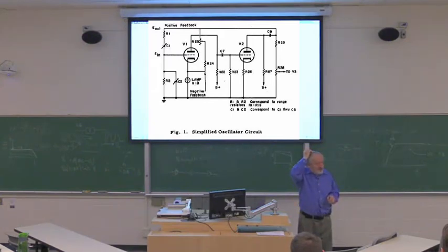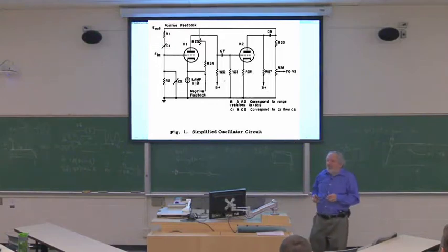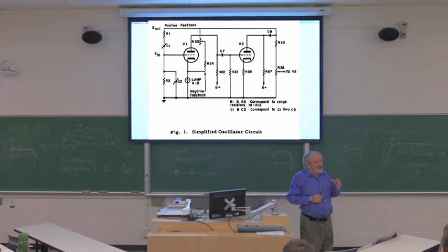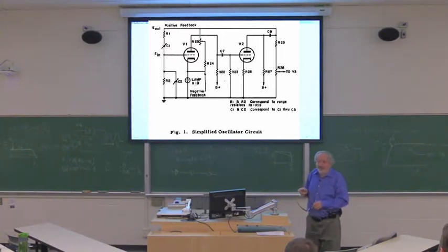So if you take a light bulb and put it in series, it becomes something towards a constant current supply or a current regulator, because if the current wants to go up, the light bulb starts getting hotter. As it gets hotter, the resistance goes up and limits the current. So one of the earliest types of current regulators was just a light bulb.